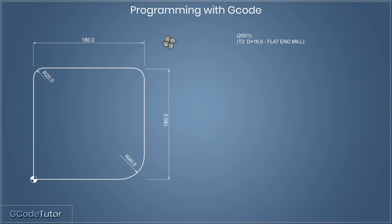Moving on to the next line, we have another operator's note. Everything is in brackets on this line, so it's not machine readable. This is purely for us, so the operator knows what's going on. So the information we're telling ourselves on this line is that T3 is the number of the tool we are using, D is the diameter, and then a description of the tool. And we end with end of block to tell the machine this is the end of the line.